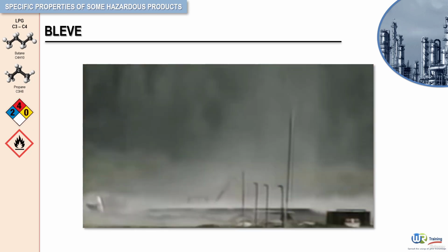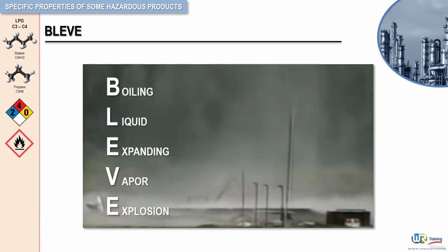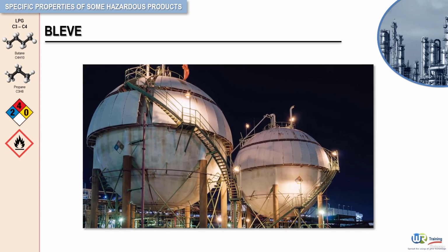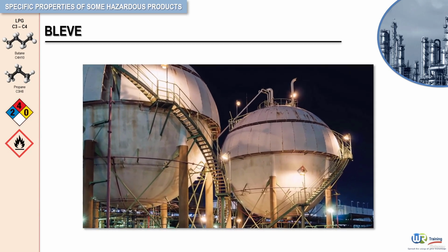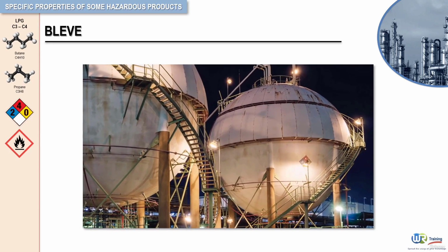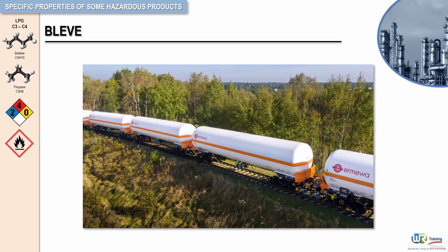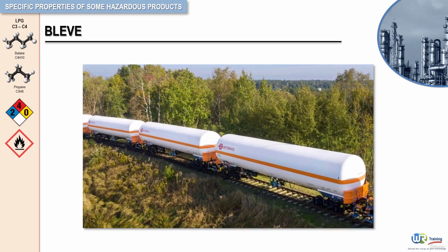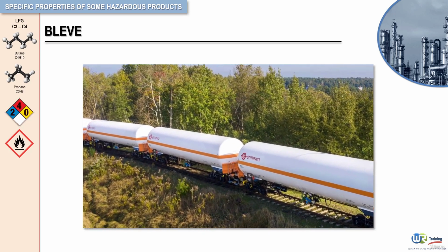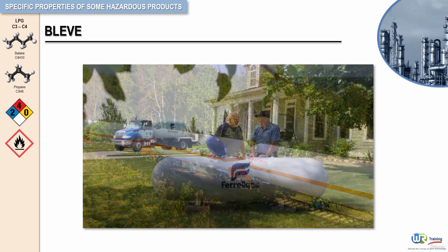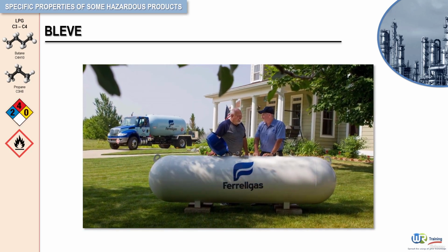What you have just witnessed is a BLEVE. The term BLEVE stands for boiling liquid expanding vapor explosion. Now, we find liquefied gas tanks everywhere around us. There are approximately 1 million propane storage tanks and 14 million refillable cylinders in use across the US, including in our own backyards. Yet, because of their sturdy construction and safe storage and handling practices, very rarely do we ever have a tank BLEVE.